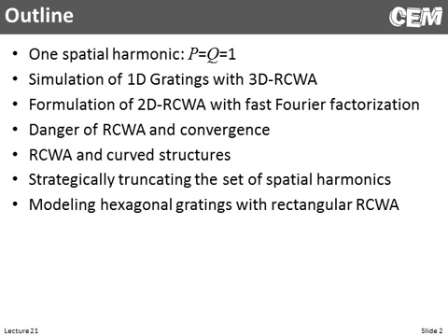The next thing is a danger in RCWA. Conservation of energy is very good no matter how many spatial harmonics we use. In real space methods, if we limit the number of points in the grid, there's some real obvious signs that things are going wrong. RCWA does not have those signs, so having a habit of always checking for convergence is very, very important here.